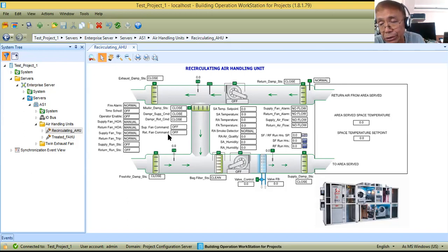Now, the fabricator will give you these points through a relay. So the contact of the relay, volt-free contact, will be given to you. When it is running, from the auxiliary contact of the motor control, they will connect a miniature relay so that if that relay is activated, the normally open contact will be used for the BMS monitoring points. Okay, I hope you have an idea what I'm talking about.